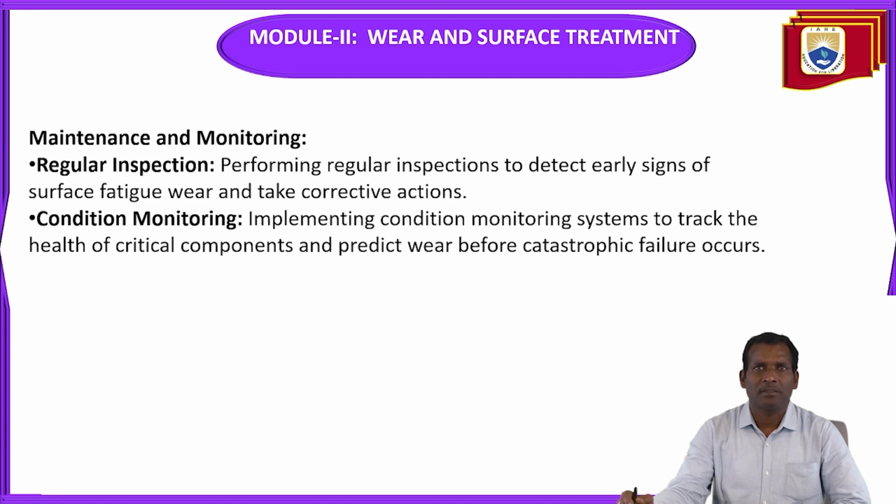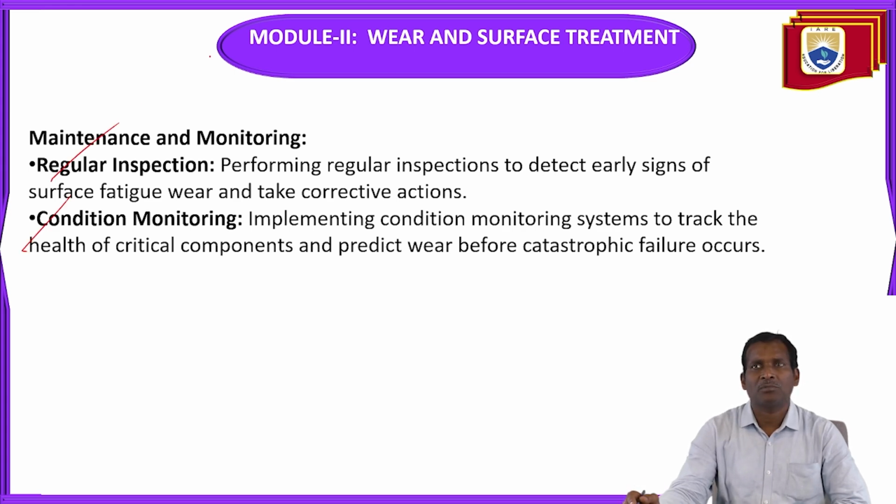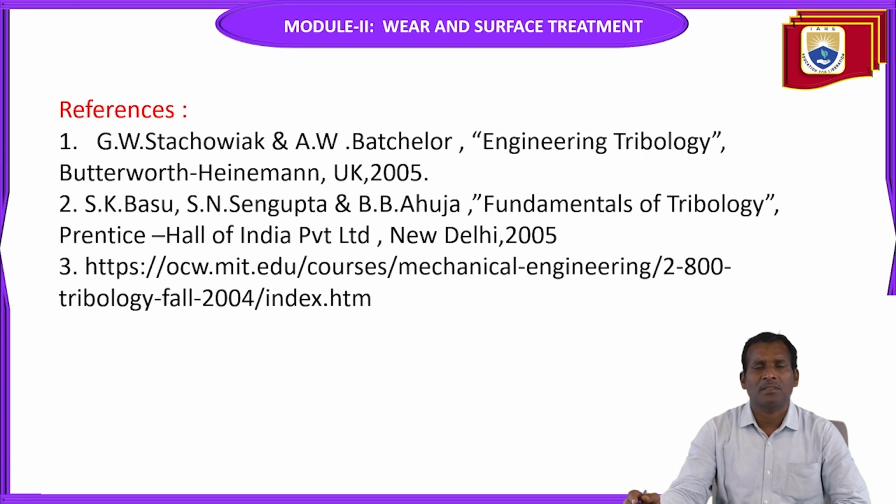Regular inspection to find early signs of surface fatigue wear and take corrective actions to reduce wear and friction. Condition monitoring: implementing condition monitoring systems to track the health of critical components and predict wear before catastrophic failure occurs.